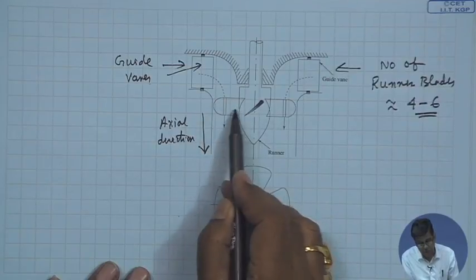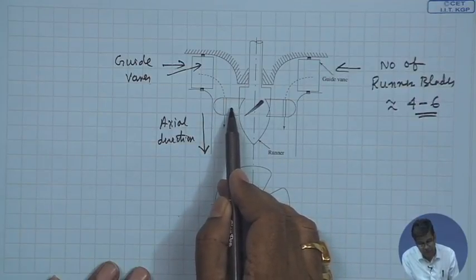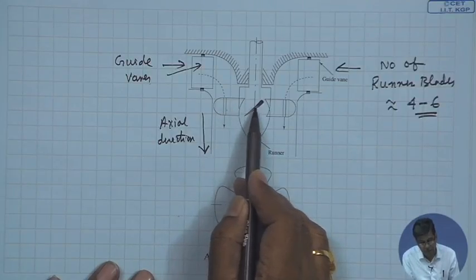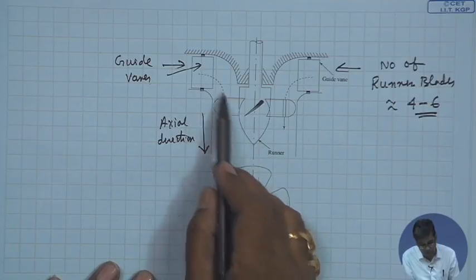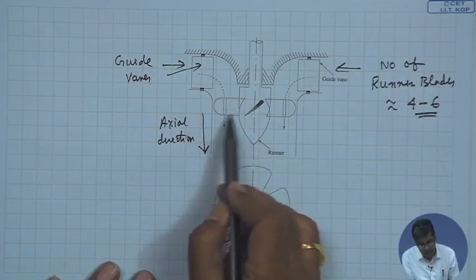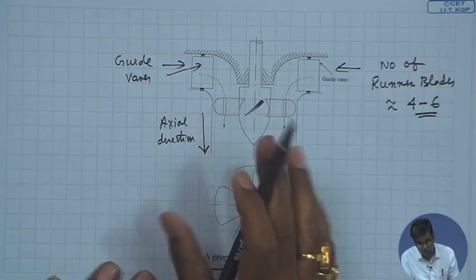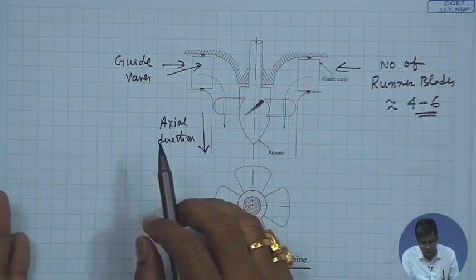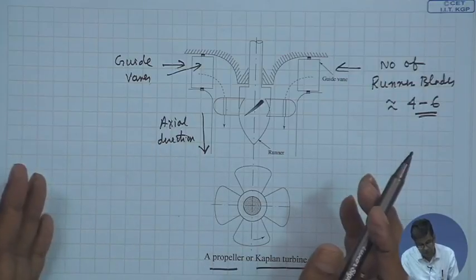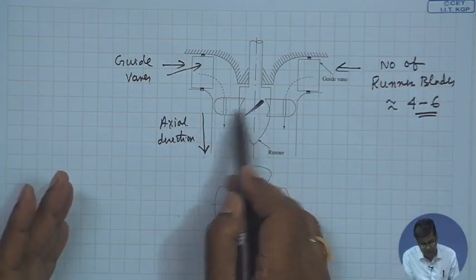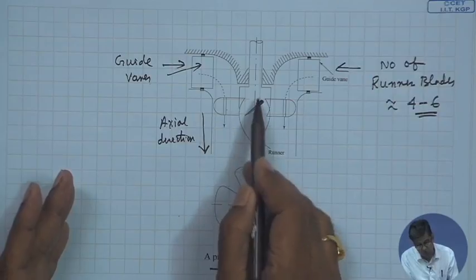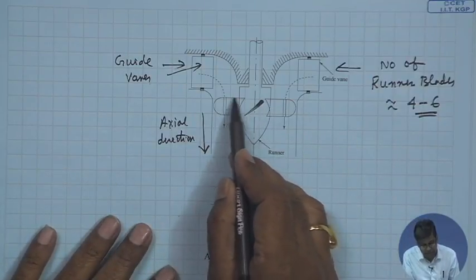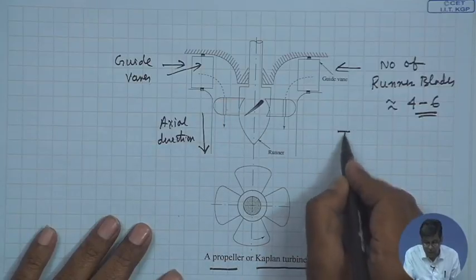That means solid body rotation, where the linear velocity is proportional to the radius of rotation, that means the radial location from the axis of rotation. A combination of these makes a complex flow of a typical Rankine vortex type, which is a mix of solid body rotation and the free vortex flow. So, away from the center there will be free vortex flow, close to the center of rotation is the forced vortex flow, and to take care of that these blades are made twisted.